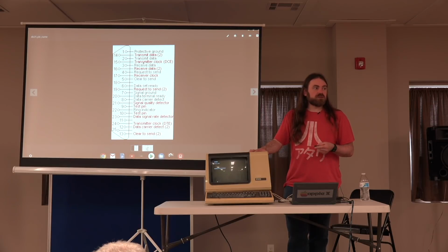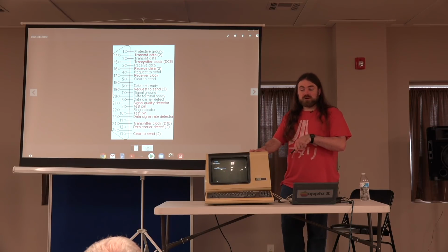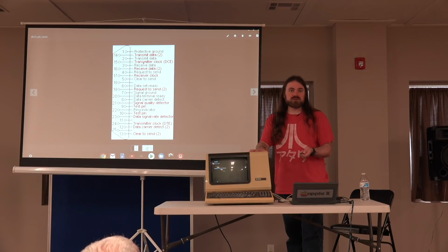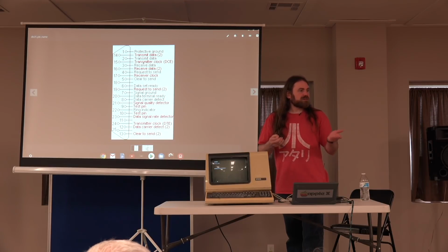Yeah, you can definitely run at that distance. For even longer distances, they would use current loop, and current loop is what a teletype uses. It's the same sort of signal as RS-232, but with different voltage levels, and instead of voltage pulses, it's current pulses. But you can convert between the two. They would also run higher voltage, and that higher voltage over current loop lets you run a lot longer distance. Almost as if you wanted to build a system of telephones.